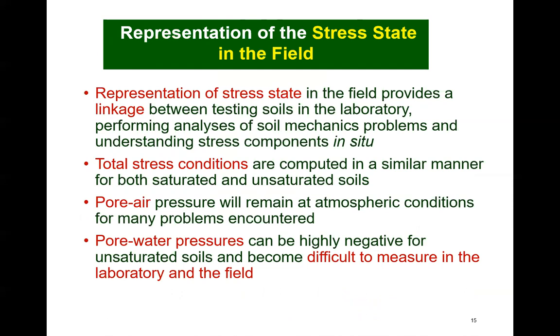Total stress conditions can be computed in a similar manner for both saturated and unsaturated soils. This is good news. The pore air pressure also will generally remain near atmospheric conditions for most geotechnical engineering problems. This is also good news. It is the pore water pressure, however, that can be highly negative for unsaturated soils and can be a challenge to measure both in the laboratory and the field.